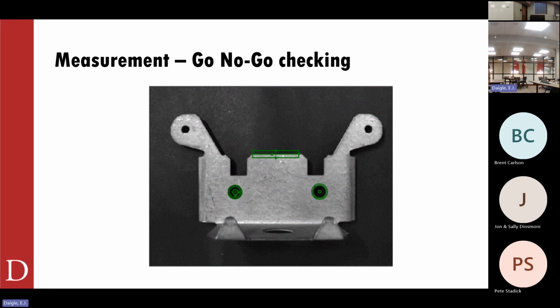So I can see there's also a bend, and part of this part's coming up at me. When I'm going to use this in a machine vision system, we may want to take measurements on the flat here, but this is a little trickier here, right? I can't measure that hole from above. I either need some sort of 3D machine vision system, or I might have another camera shooting in from this side or shooting in from that side.